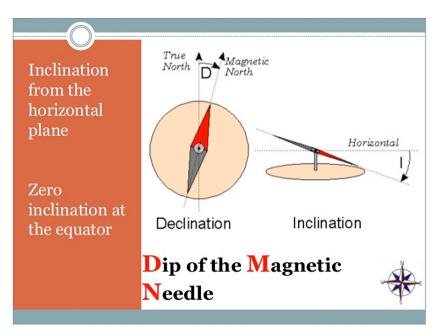In this particular slide you will see that the declination is the horizontal angle between true north and magnetic north. Similarly, when you consider the same figure in vertical section, and observe the inclined position of the magnetic needle, the needle makes a vertical angle to the horizontal position.